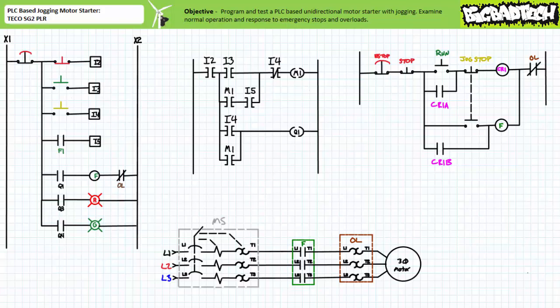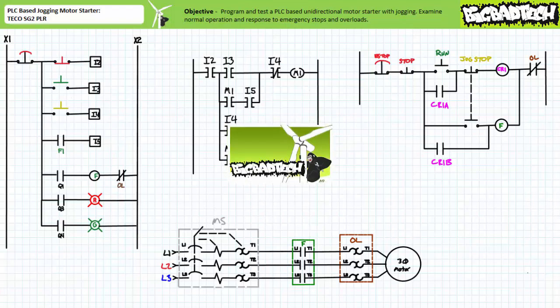If either scenario is untrue, either because the system is at rest and someone is forcing the F contactor closed, or while the system is running and an overload event directly de-energizes the F contactor coil, the holding circuit will not be established, or if previously established, will be broken. The third and final implementation of the PLC-based 3-wire motor starter lecture, available at the Big Bad Tech channel, discusses this modification in greater detail if you wish to review it.